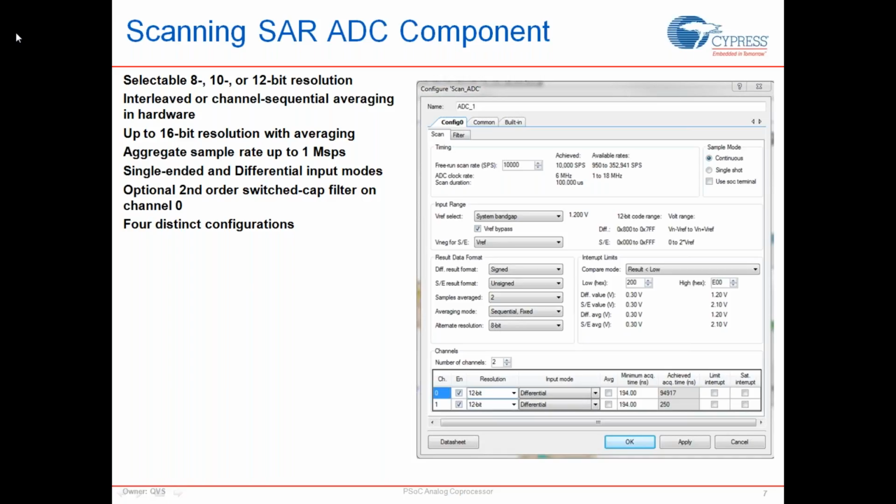If I have interlaced sampling, after I'm done with channel 1, I go to channel 2, sample once, and then go to channels 3 and 4, and back to channel 2, and then sample it one more time. And thus, I keep going for 256 iterations, and then get one output out of channel 2, while I'm not affecting the actual sample rates of channels 1, 3, and 4. So those are the two types of sampling, sequential and interlaced. Depending on applications, you can use either of these.